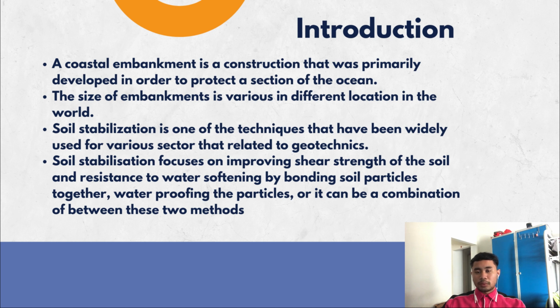Next, I will present about soil stabilization. So soil stabilization is one of the technique that have been widely used for various sectors that are related to geotechnique. So soil stabilization focus on improving shear strength of the soil and resistance to water softening by bonding the soil particle together, waterproofing the particles, or it can be a combination of these two methods.